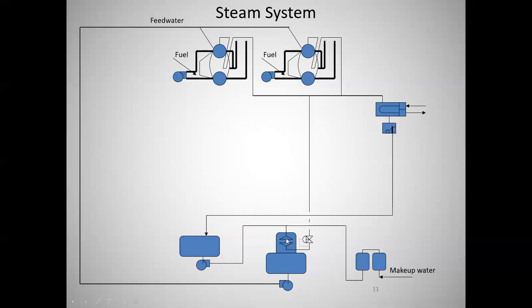It's really up here, and then this is a tank that, once the gases have been stripped off, it gets stored here, and then it gets pumped back to the boiler. Okay, so you see this condensate comes back, and it comes over here and goes through the deaerator, and this is your makeup water, because guys, whatever steam you put out here, you don't get it all back. You may want it all back, but you won't get it all back.